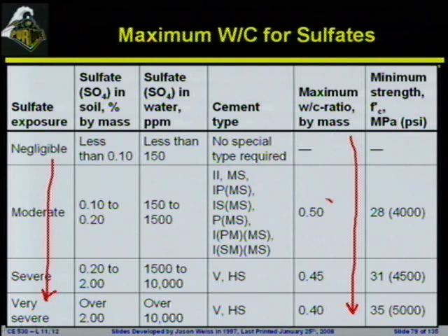You're going to see it in the 0.5 range. It's going to drop down into the 0.45 range, and the 0.45 range is significant because this is where we start squeezing out the capillary pores, 0.42, 0.45 in that range. And then we're going to drop down to 0.4, where it makes it very difficult for things to be transmitted through the system.